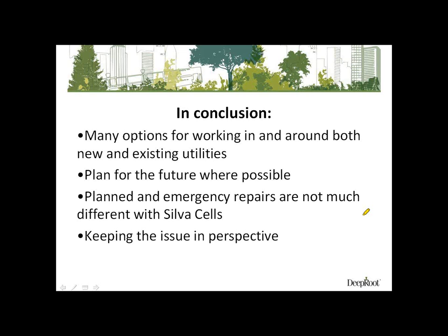Some people have experimented with the different types of medium that the Silva Cells are filled with. Like I talked about, some are layered systems, some are rock, some are sand. We've had some people experiment with the void space. We typically fill the Silva Cells all the way to the top, but in some cases people are leaving a gap at the top for a ponding area to increase the volume and hold the water for more volume for a longer period of time. In other words, so that they can take bigger volumes or bigger storm events.